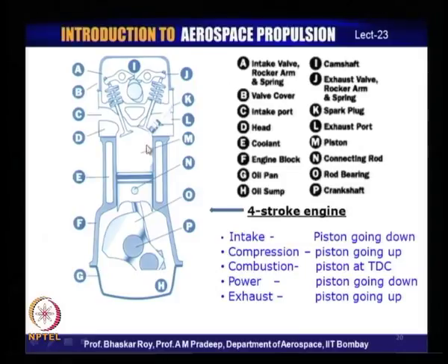It is timed to open when the piston starts moving upwards after the power stroke, and then the burned gas. Now, this is closed. So, this is burned gas. The work has been taken out through the power stroke, and then this burned gas goes out of the cylinder altogether, and this reaches top dead center, and almost the entire amount of burned gas is now moved out of the system. What does happen is a very small amount of burned gas actually stays back.